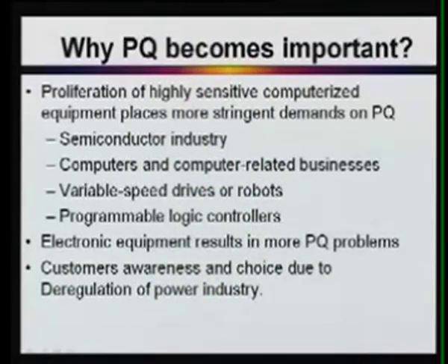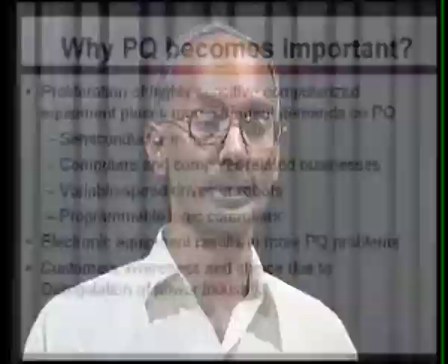So let us see the power quality problems and their effects. Already we have seen the various power quality disturbances: voltage dip, voltage swell, phase angle displacement, transients, harmonics, and electrical noise. Now, the effect of voltage dip is the maloperation of power-down sensing circuitry in computers and controls, variable speed drives, and computer trip-out. Sometimes a variable speed drive controller, if there is a voltage dip, may not work properly because it senses the voltage, and that voltage is used for firing circuit utilization.